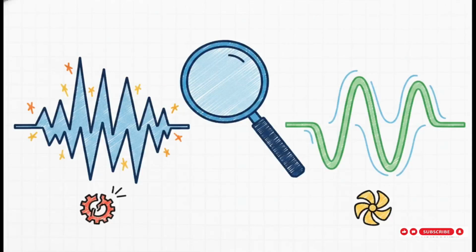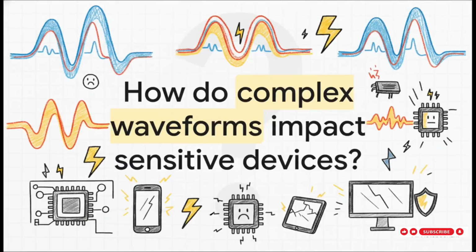Now, what's really fascinating here is how these two terms act as the ultimate summary of a wave. The form factor is simply the ratio of the RMS value we just calculated to the average value. The peak factor is the ratio of the absolute maximum, or peak value, to the RMS value. By just looking at these two simple ratios, engineers instantly get a quick mathematical profile of a wave's shape. They immediately know if a wave is spiky and potentially damaging, or smooth and deficient, all without having to graph the whole thing out.